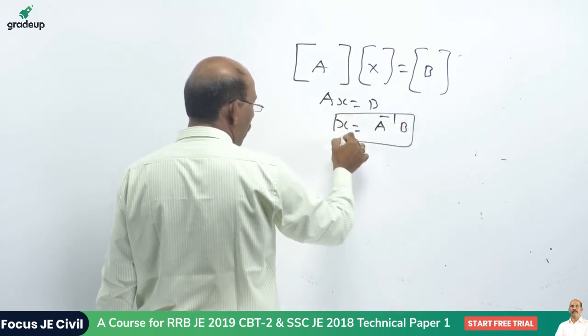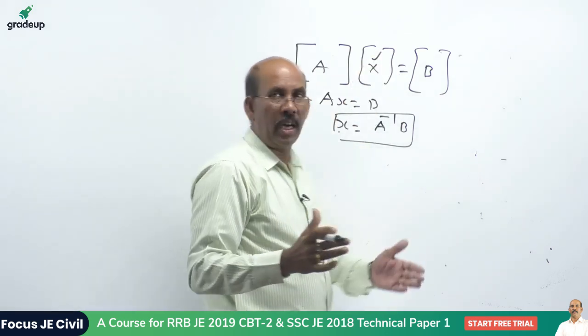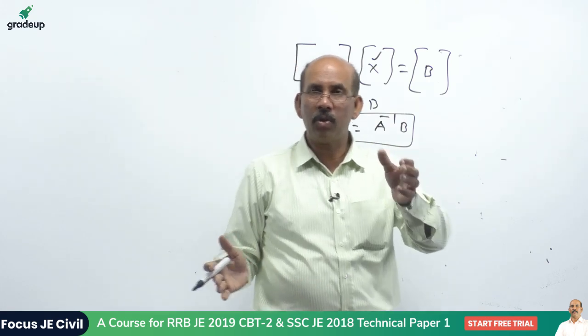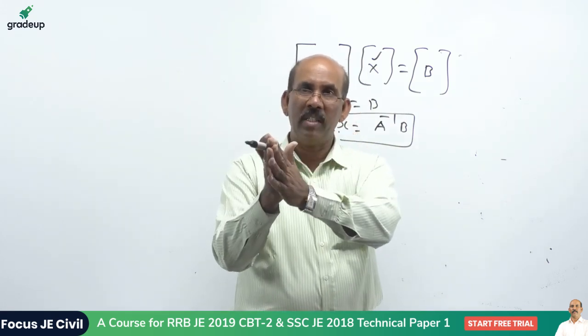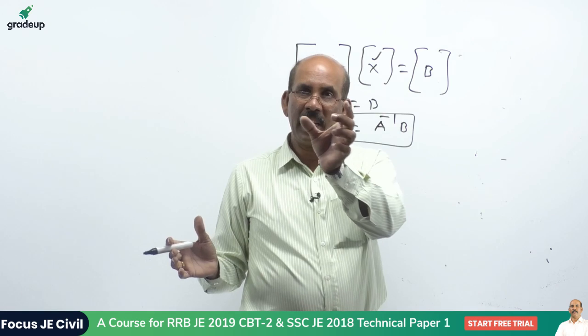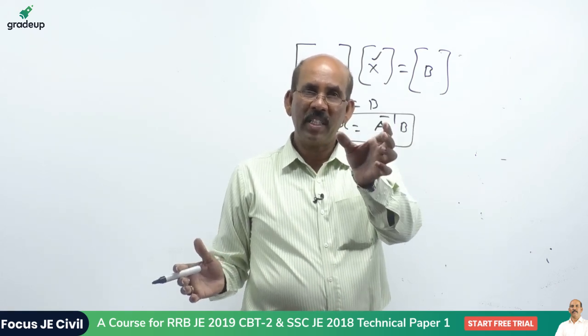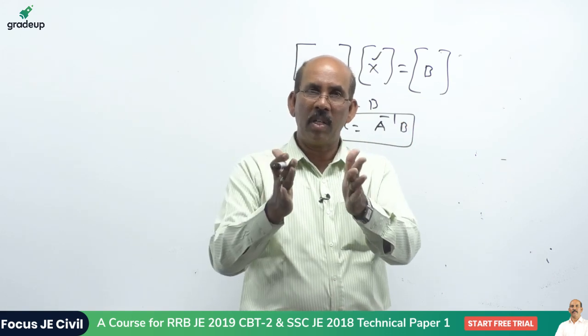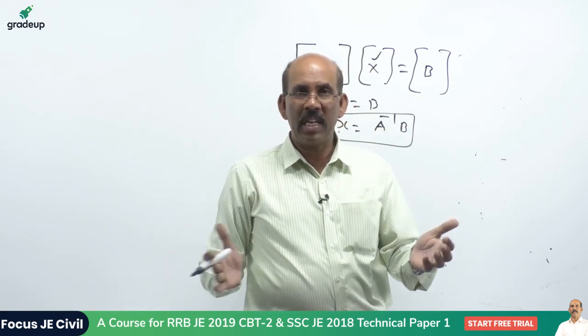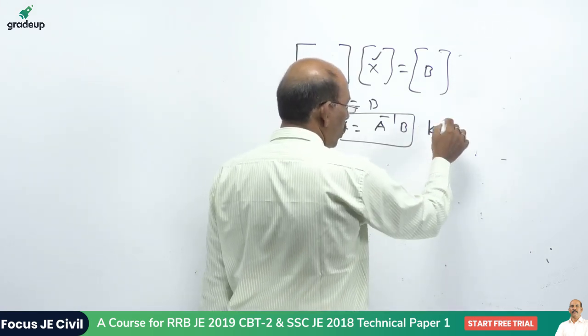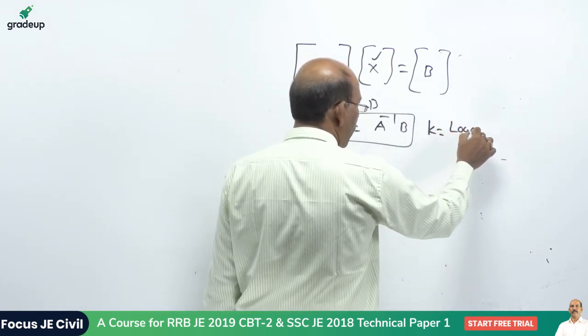So this particular one, x values in the stiffness matrix, the two important things, one we have to see the load, another one is the deflection. In the case of the slope deflection methods, your equations are in terms of the angles. Same thing here, the stiffness refers to K is equal to the load causing unit deflection.